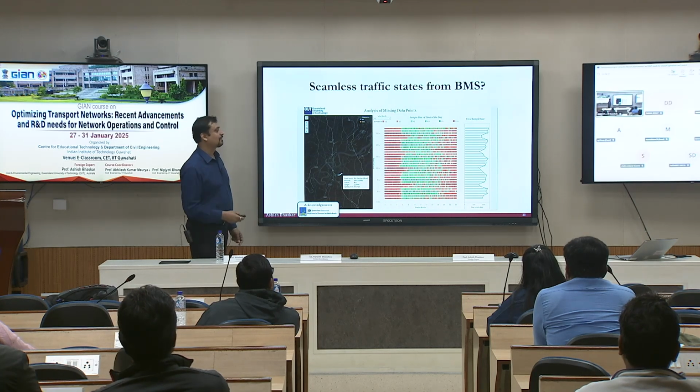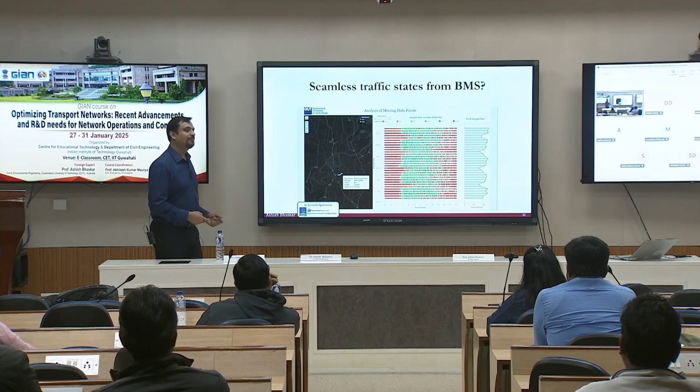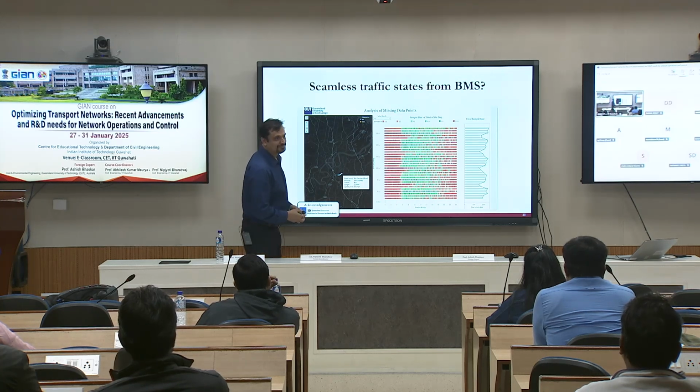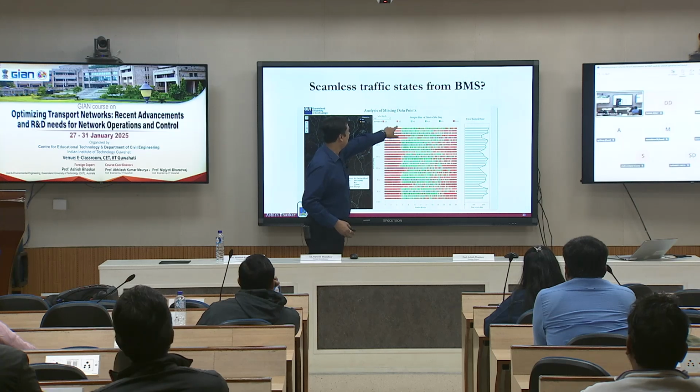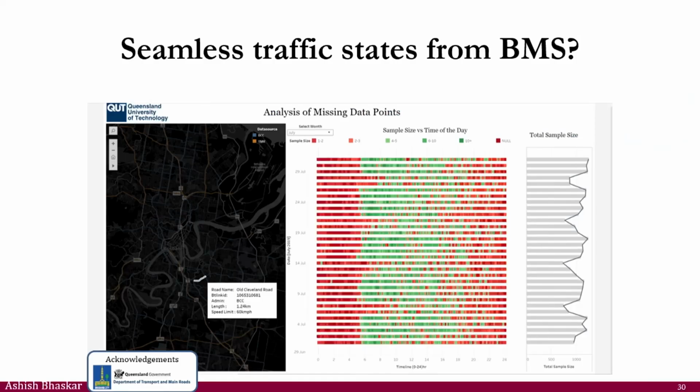This one, sample size is low here. It's a single lane. So red means sample size is between, let's say, 1 or 2 or 2 or 3 every minute. So every 1 minute you are observing only 2 or 3 samples. By the way, I'm saying it is low, but from the perspective of traffic engineering, it's a very good sample. There's no way you will get that detailed information for that time period. But it is a low sample, it means that I will have less confidence.